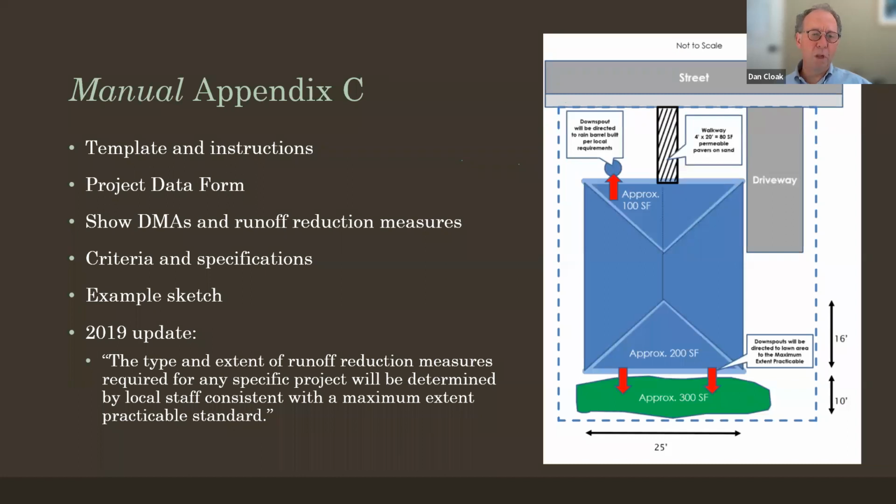And you really want to do that because, particularly in more densely developed sites, more urbanized areas, you don't want to give up landscaped areas that are adjacent to the building from being used as bioretention facilities. It makes your overall compliance too difficult if you do that.